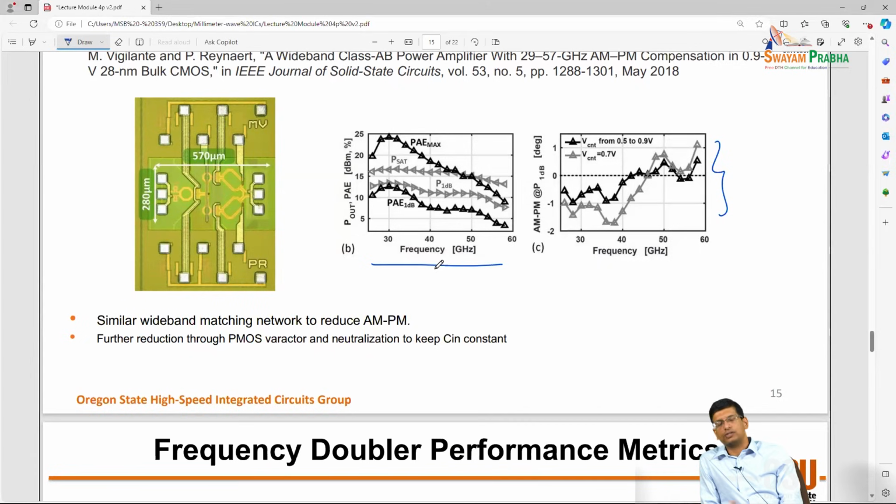So of course you have to make sure that the PA is small signal stable, right? And look at it across all frequencies, not just the band of interest, because very typically the PA can go unstable at low frequencies when you're designing for millimeter wave. That conventionally happens. The challenge is that the PA is usually operating in large signal, so you see small signal stability, but you don't see large signal stability.